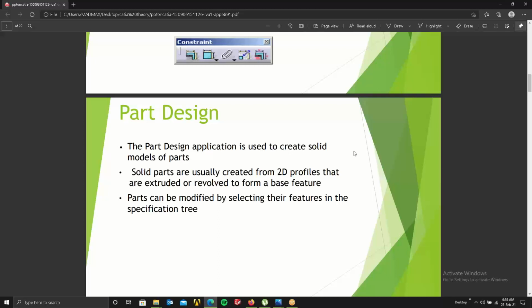Yes. So you can constrain it completely using dimensional constraint, no problem. But there'll be a lot of lines and things in your sketch you won't be able to understand. You'll go crazy. So better than that is you can use geometric constraints. So like I said, if you have a circle and if you have multiple objects and everything, so directly if you give symmetry, you don't have to constrain the rest. Symmetry is a geometry constraint. So if you give symmetry, you don't have to constrain anything else. Only one single part if you constrain, that is done.